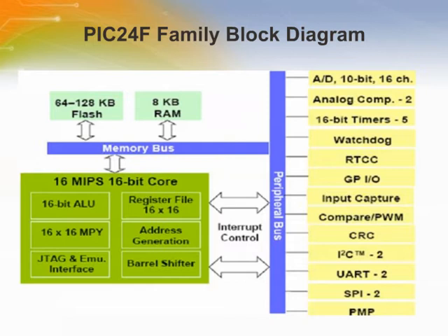The PIC24F family also includes a real-time clock with calendar function that is often used for time-stamping data logged information or communications data. The devices also include 2 I2Cs, 2 UARTs, and 2 SPI channels. To complement the various serial channels, there is also a cyclic redundancy check, CRC, peripheral that can be used to ensure data will be correctly communicated.